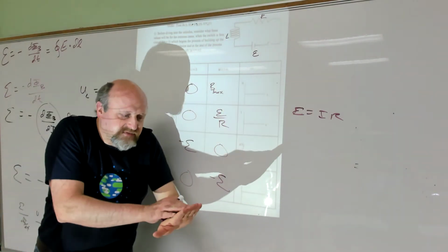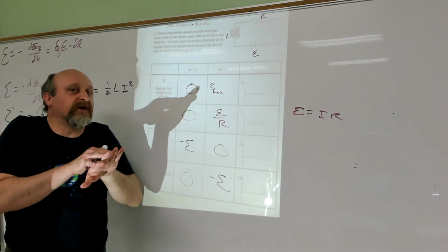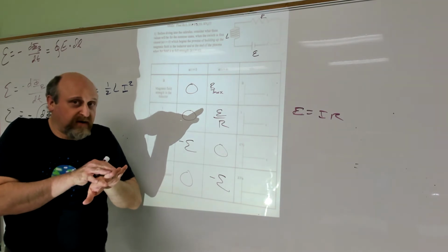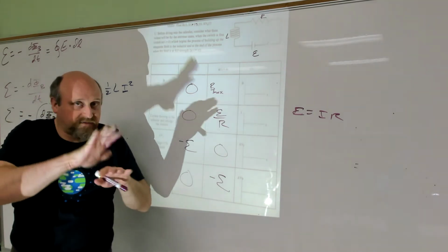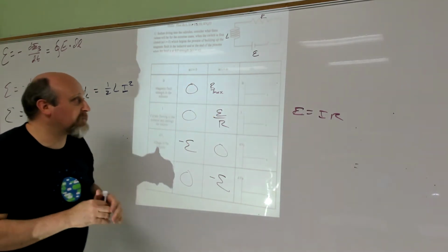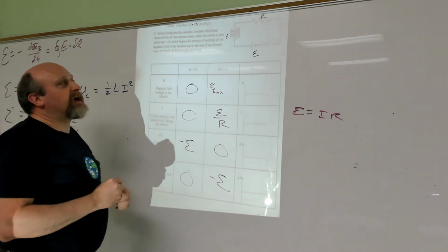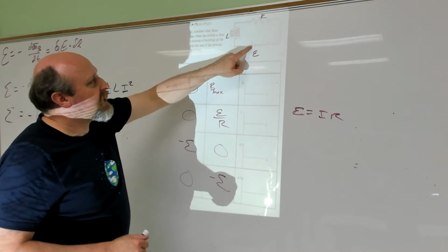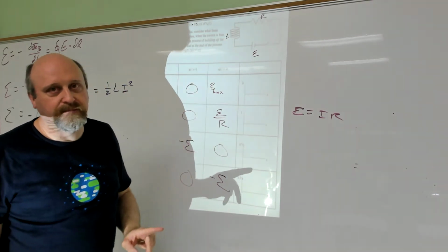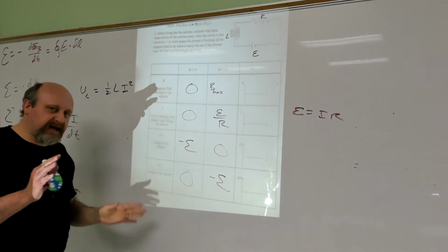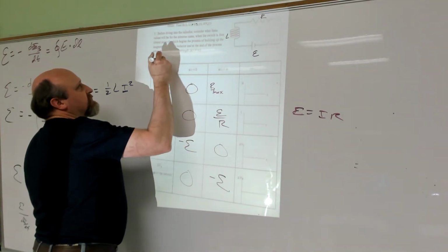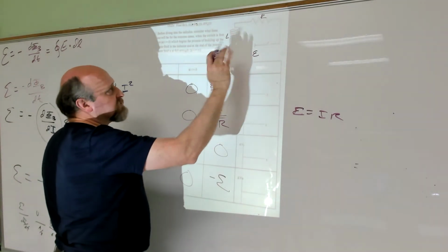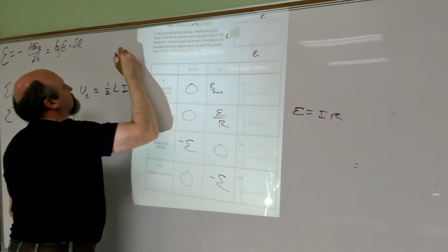So it makes you have to build up from the current you were at, okay? It makes it so you can't jump currents. So the current value has to slowly build up. That's what it does. At the end, it's not fighting against the current at all. So at the end, it acts like a bare wire. This is the inductor when we are closing the switch or turning the circuit on.